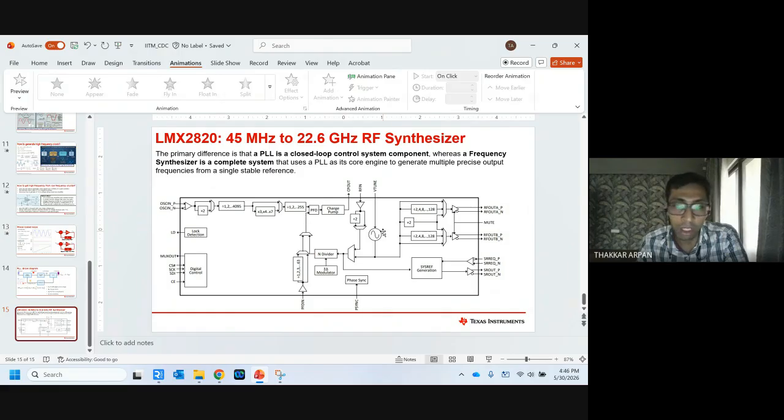Whatever you do across wafers, there will be mismatches and all that. So you can never get constant frequency in terms of ppm from on-chip oscillators. So what will happen if I don't put anything here, and I just apply some constant tuning voltage here?